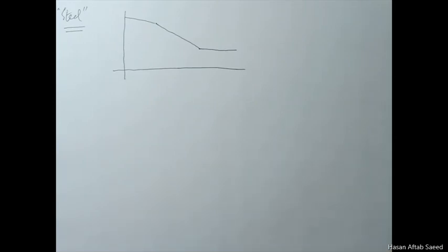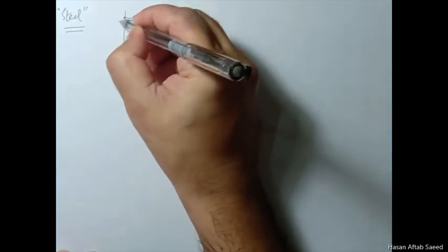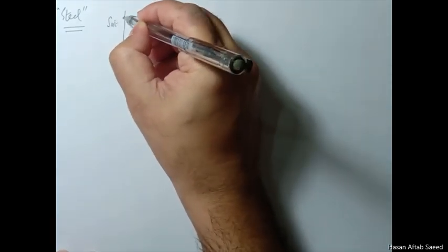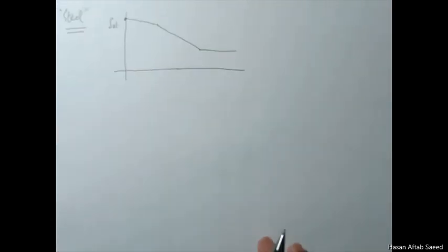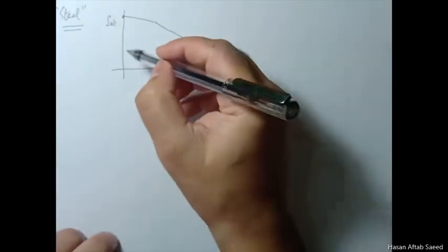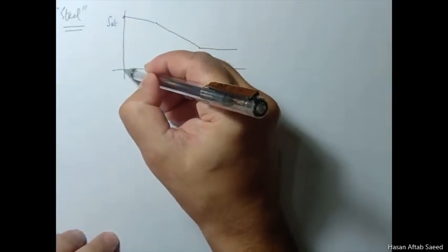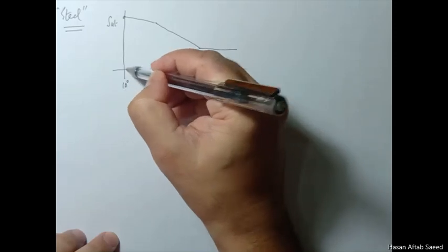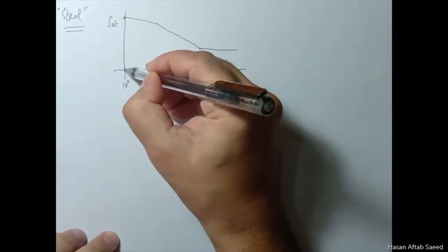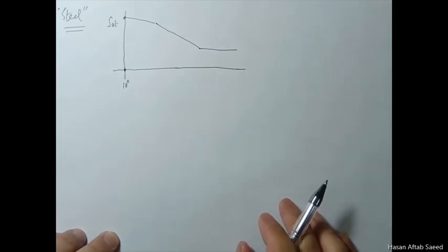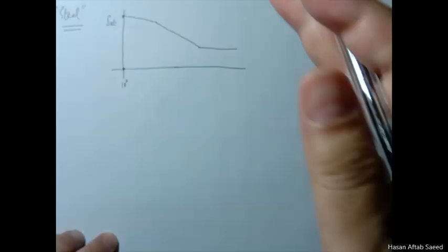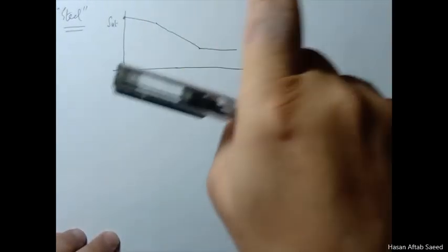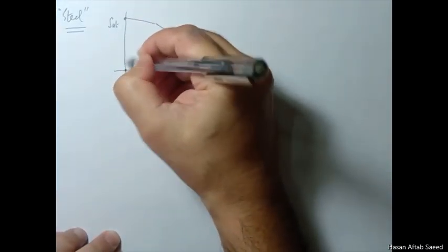So the first thing to note is that here this is equal to the ultimate tensile stress, or ultimate tensile strength of the material. And that it's very obvious. How many cycles are there? There's 0 cycle here, or you can say 1 cycle. If you load something to its ultimate tensile strength, how many cycles do you need for it to break? Actually it is less than 1 cycle. It's maybe a quarter of a cycle, because you don't need to come back. It just breaks in maybe a quarter of a cycle. But we put it at 1.